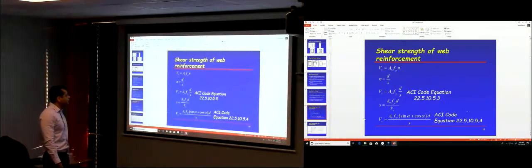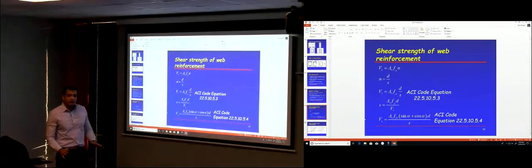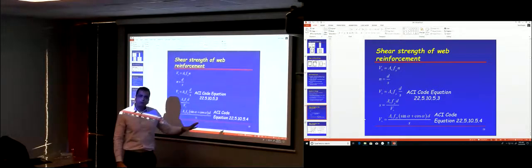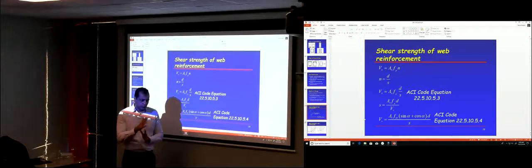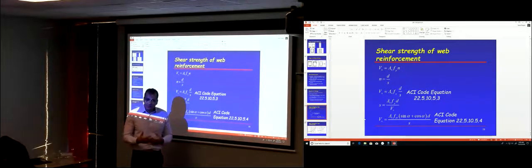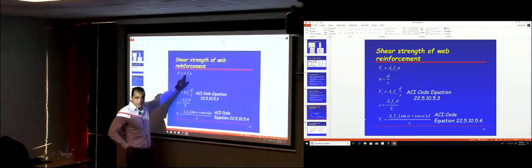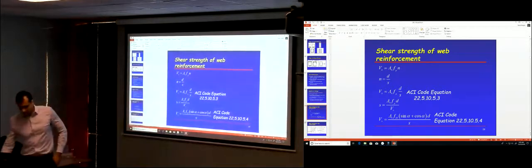This is the design equation we mentioned last time. So you have the shear force. Part of the shear force will be carried by the concrete, and we know how much the concrete can resist. And now for the stirrups or the bent up bars or whatever type of reinforcement you're using, okay, how much V_s, the strength that the stirrups or the steel can provide, it's V_s, it's A_v, the area of those stirrups, multiplied by the yield stress of those stirrups at yield tension, multiplied by the number of the stirrups along the crack, okay.